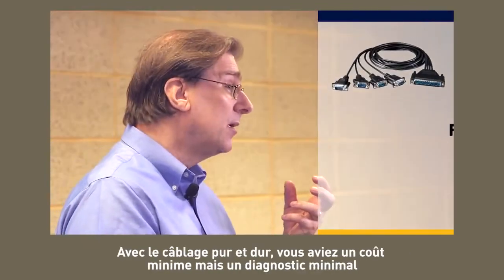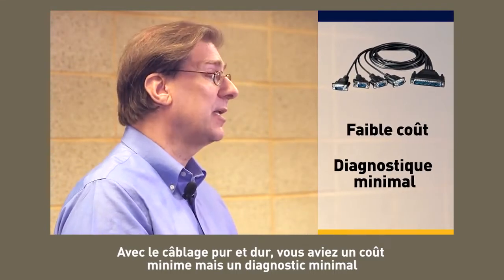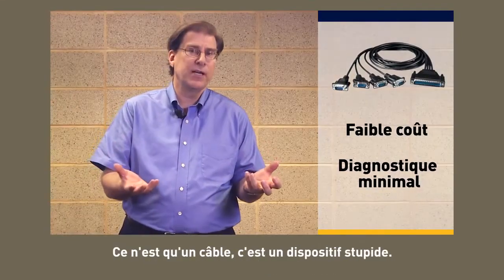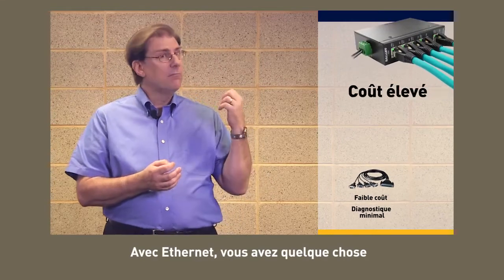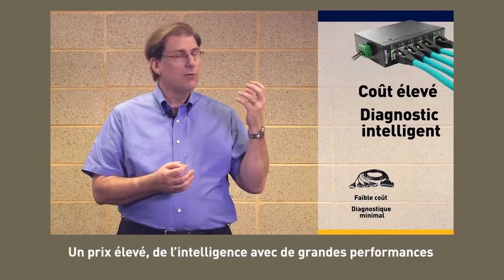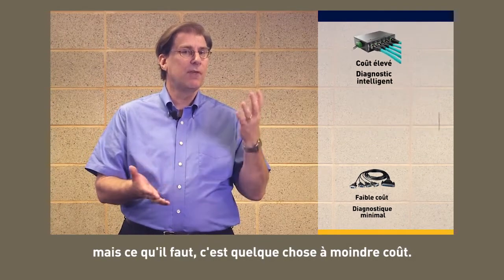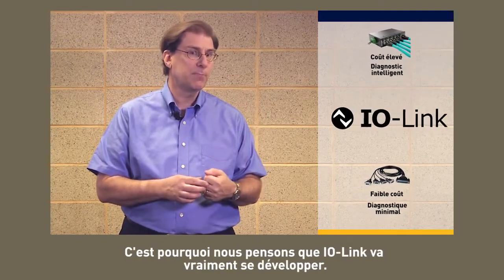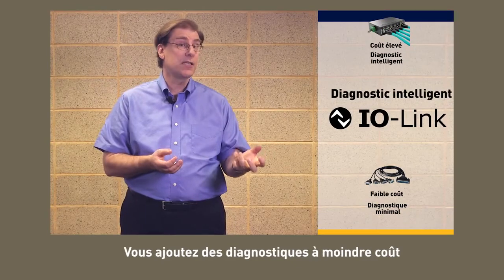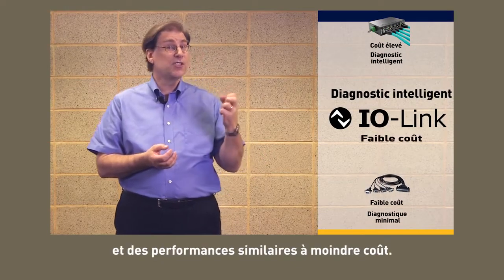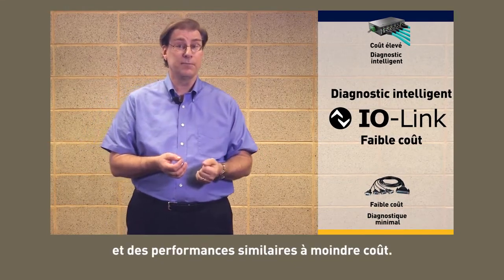Hardwiring had minimal cost, but you had minimal diagnostics. It's a hardwire, it's a dumb device. You had Ethernet, high priced, smart, great performance, but you need something that was a little lower cost. That's why we think I/O Link is really going to expand. You're adding diagnostics at a lower cost, and it's a similar performance at a lower cost.